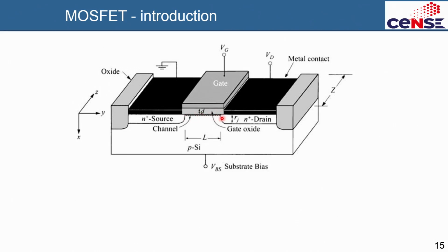forming here. For the current to flow here now you need a field, a drift kind of transport, such that the electric field will drive this high density of inversion charge that has formed here from this point to that point. So electrons have to flow, so current has to come out.